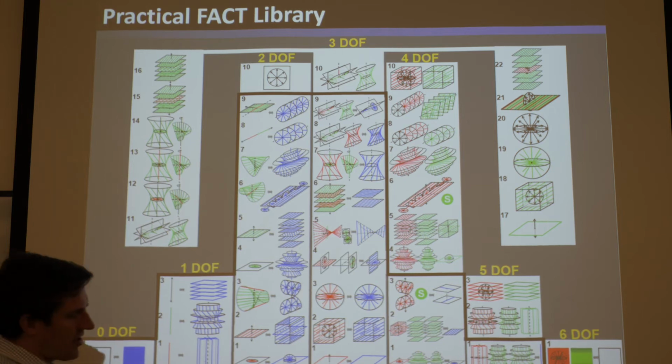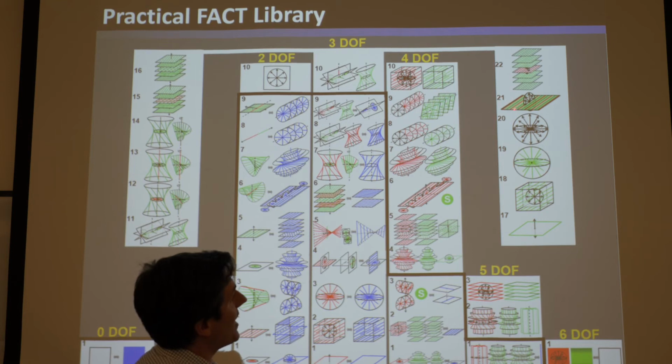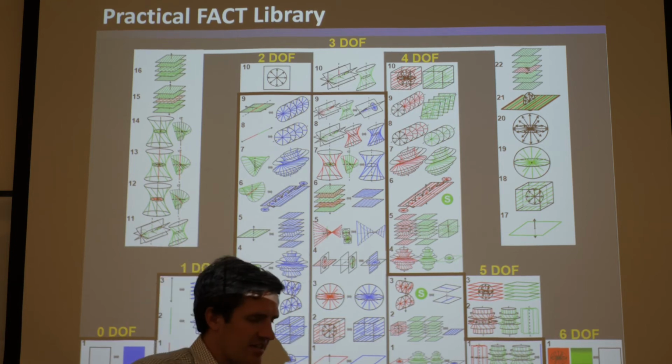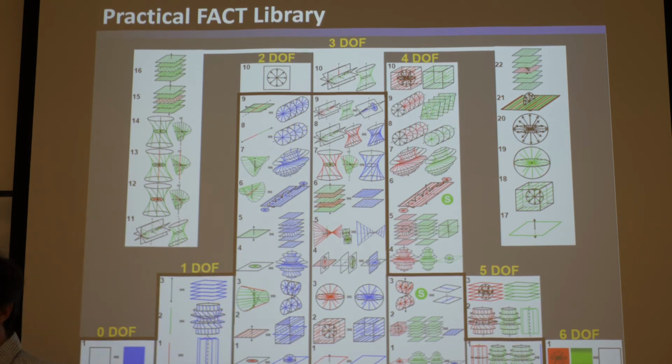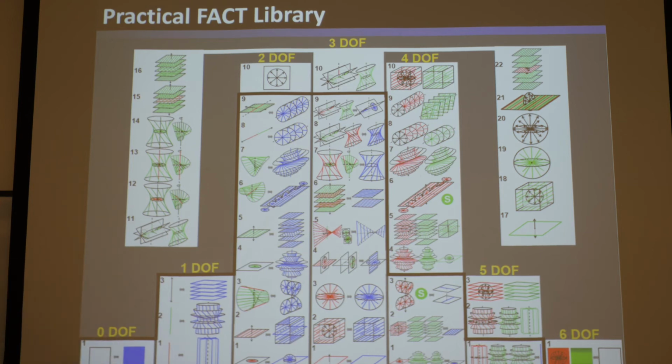If you're curious and want to look back at that example, I believe it's 3DOF type 21 that is the freedom space I was asking you to design. You can see here this freedom space, 3DOF type 21, doesn't have a constraint space. So there's no parallel flexure system that could achieve that, and that's why you couldn't stick a single wire in to get that motion combination.